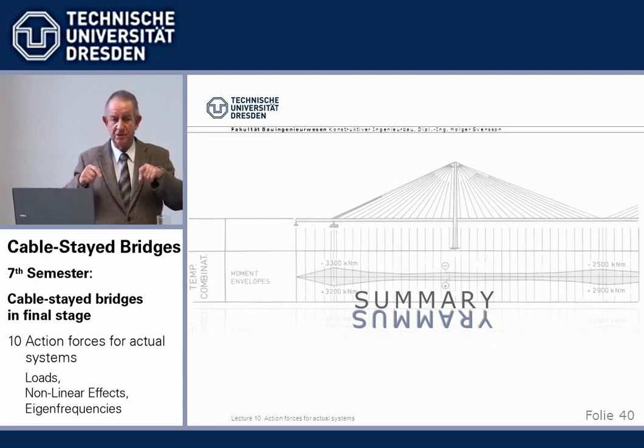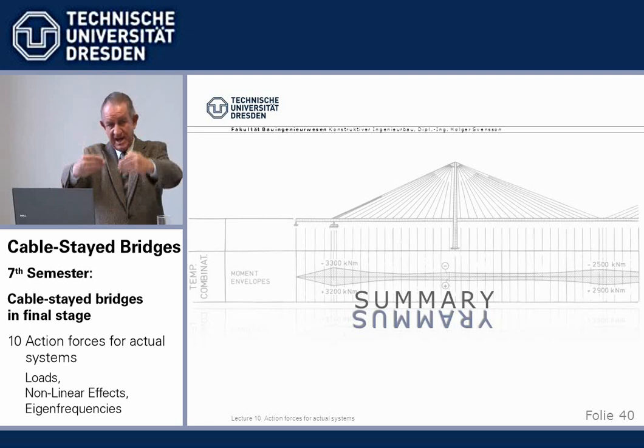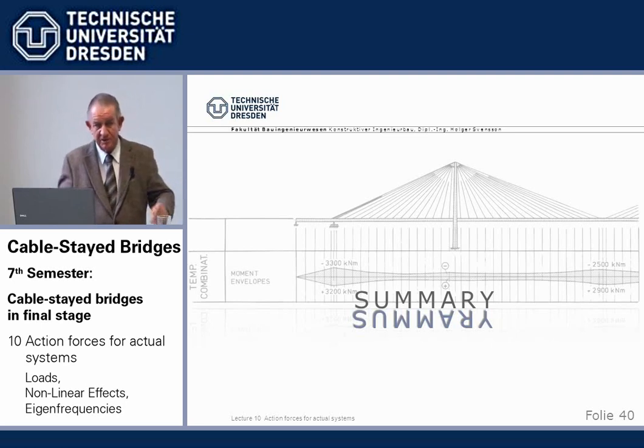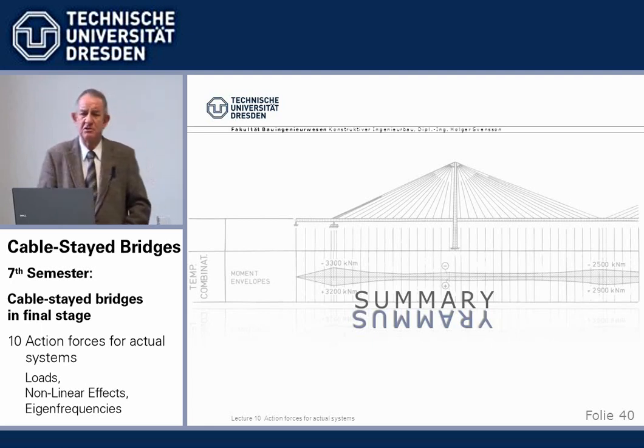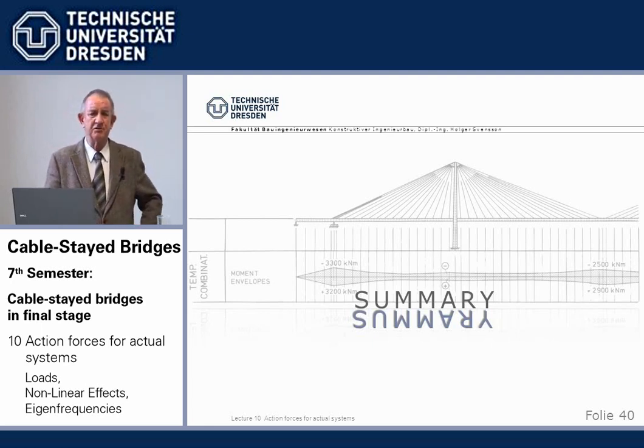And then you tell the computer, give me a set of cable forces, give me a set of cable shortenings, which in effect, if added to the dead load on the elastic system, give me this run of moments on rigid supports. The computer gives that to you, and you can come there by iteration and all sorts of things. But I expect you to understand that.